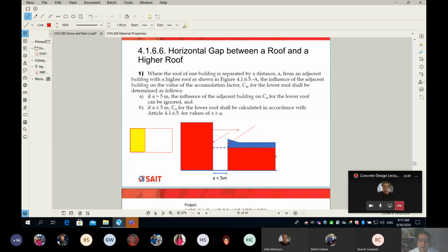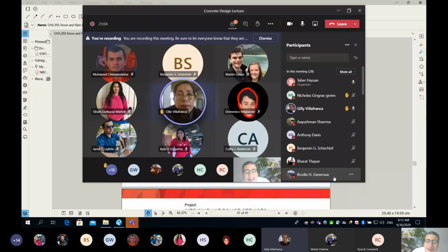What if I have here on this building a canopy? You guys know what a canopy means, right? Let's say my building entrance is from this side, and we have a canopy, and the canopy, for example, is hanging by a cable to the building. So let's say this is a canopy. I'm asking you, what do you expect here on the canopy? Do you expect uniform snow or expect accumulation? Please talk. Accumulation. Okay.